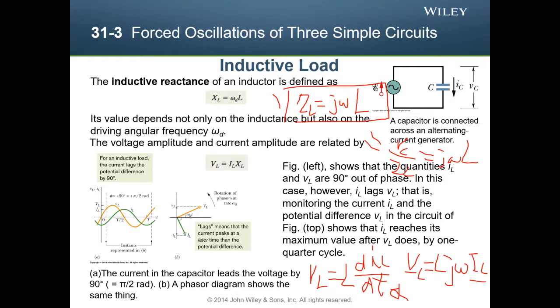You can just simply change the RLC into the phasor, and then you calculate it as usual. You transform the sine wave with the frequency into its corresponding phasor, and then you calculate, assuming it is like a resistive circuit, and you get a complex number, and then you convert it back to a sine wave.